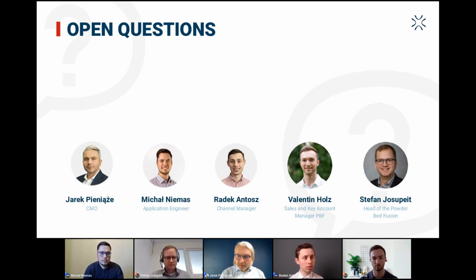And I would like to add to what Valentin said before. We have a possibility of coating PA12 and elastic parts, so you can have any of 10 colors and possibly more if you need a different color for the printout. Also, there's the option of dyeing if you want to change the color, which is in general quite difficult with darker or gray materials, especially if you want a bright white. There is a coexistence of those two technologies, but for a really bright white part, it's definitely a coating.